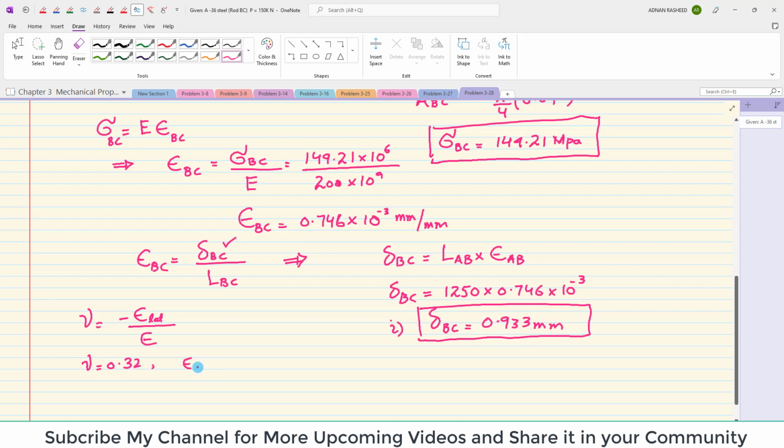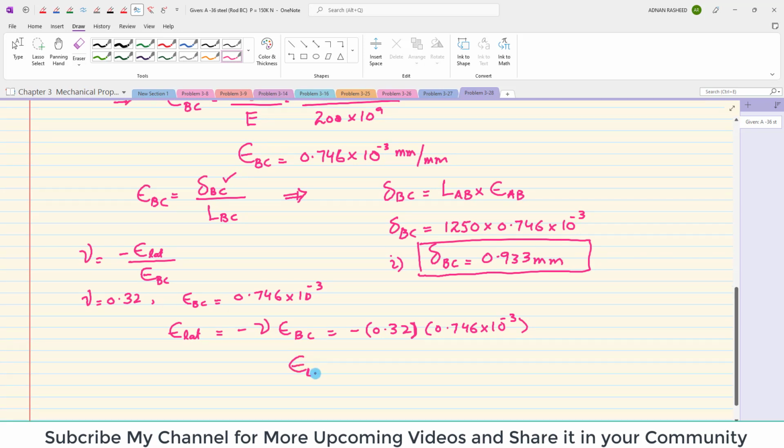So nu is equal to 0.32. Normal strain in BC, epsilon BC, is equal to 0.746 into 10 raised to power minus 3. We do not have lateral strain, so lateral strain can be found out. Lateral strain will be equal to minus nu times epsilon BC. So minus 0.32 times 0.746 into 10 raised to power minus 3. When you calculate it, lateral strain comes out to be minus 0.2387 into 10 raised to power minus 3 millimeter per millimeter.